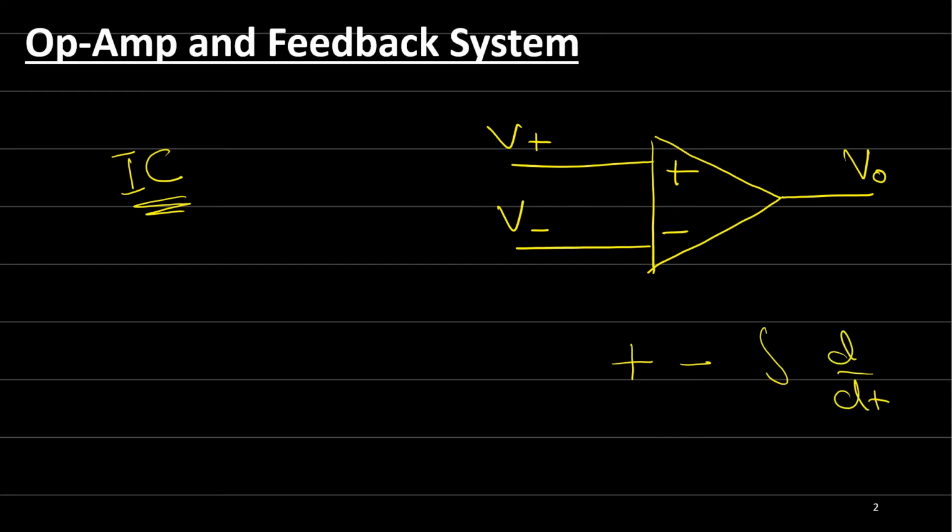As we explained before, this kind of amplifier can be considered an active electronic component. And in electrical engineering, passive components have much better drift characteristics than active components. Many efforts have been made to design a stable amplifier, but the temperature and power supply voltage limits encountered on phone lines, for example, cause uncontrollable gain changes. As we said, passive components have much better stability characteristics than active ones. Thus, if an amplifier's gain could be made dependent on passive components, the uncontrollable gain problem would be solved.